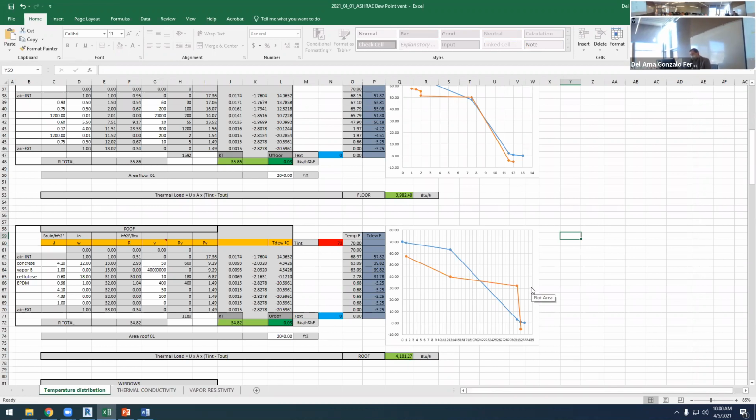And when it comes to thermal condensation risk and even thermal performance, because now we have 34. Okay, so rigid insulation in terms of thermal properties and condensation risks is much better than cellulose, but cellulose is better in terms of global warming potential. So if we are using cellulose here, that's fine. But for sure, we should be using a vapor barrier here.